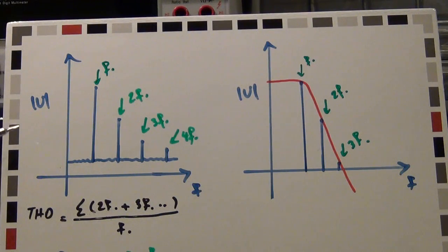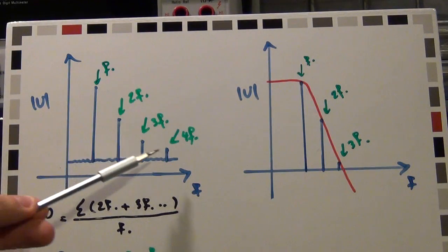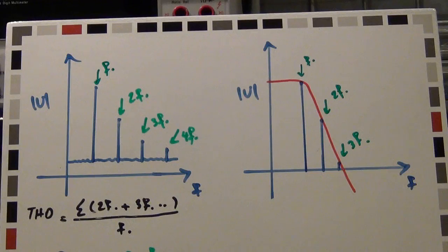You can calculate what is called a total harmonic distortion, which is the ratio of all the unwanted tones to the fundamental tone. So you can sometimes see total harmonic distortion represented in percentage, or you can see it in dB. For example, I could say that the total harmonic distortion is minus 30 dB. Means that the power of all the unwanted tones is 30 dB less than the power of the tone that we want. That may sound like a lot, but 30 dB is actually only 5 bits, so it's not very much at all.